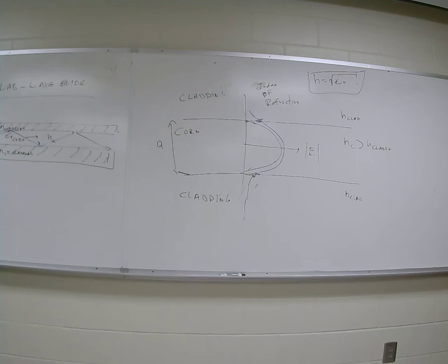Well, for a fiber optic guide, the core is round, right? And the difference for a fiber optic round guide in the solutions of Maxwell's equations is, you know how you had sines and cosines in the directions perpendicular to propagation for a conducting rectangular waveguide, right? I mean, you remember that. Well, you don't anymore. For a cylindrical waveguide, the solutions are called Bessel functions. Have you heard of Bessel functions? Bessel functions are solving a differential equation in cylindrical coordinates. All right, and that's the difference.